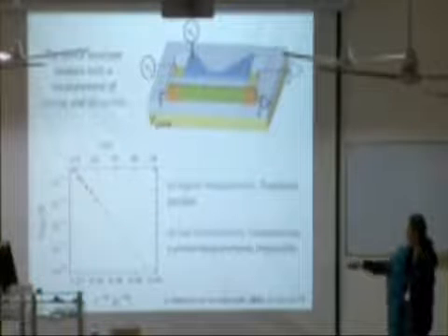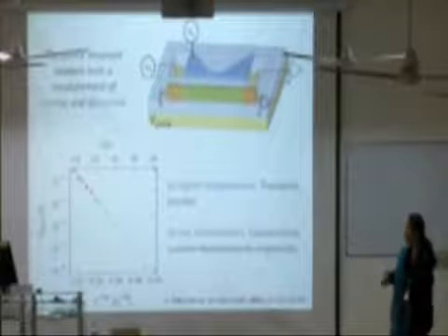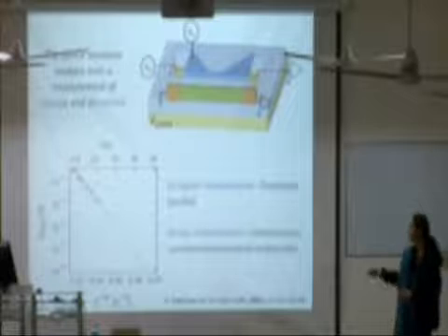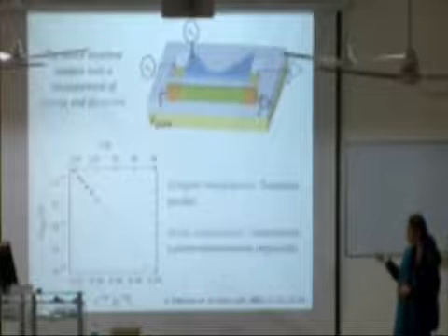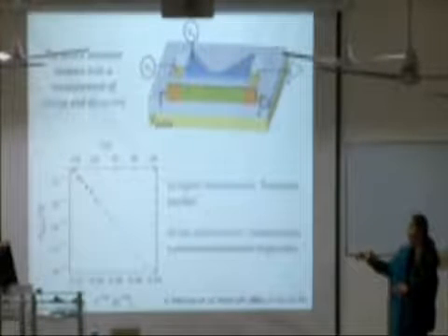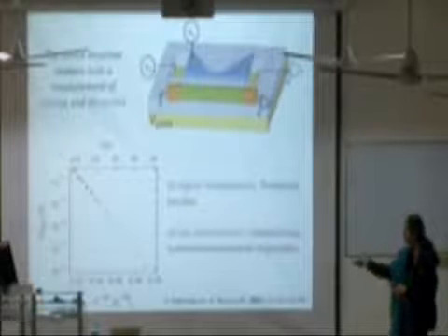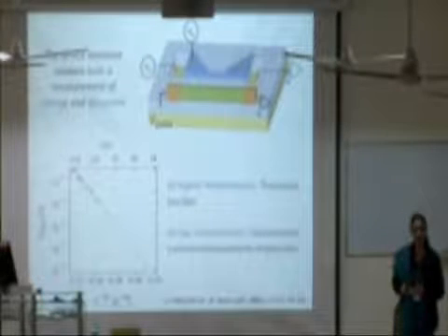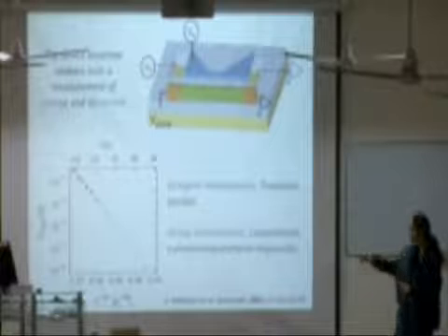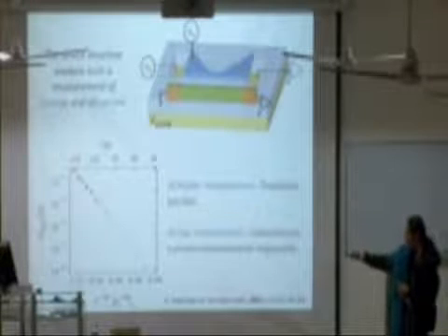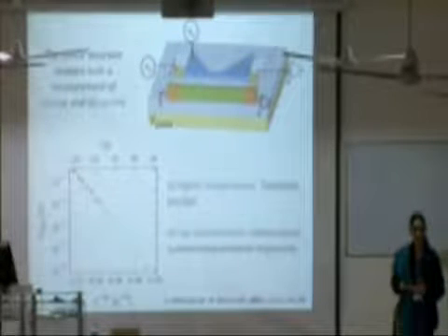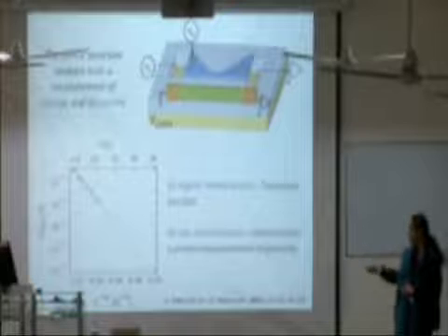a function of temperature. So the red dots are the points at higher temperatures where we can't measure our transients, but we can measure current, and we extract the conductance from the current measurements. And the blue circles are our conductance values that we have extracted from the charge sensing measurements. As you can see, there is a very small regime where both of these measurements are possible simultaneously, and there is very good agreement between the two.